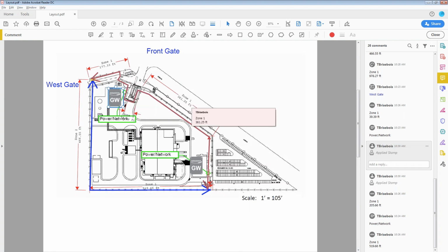One thing I do notice is that I have 2,000 feet of perimeter. So what I can do, depending on the customer situation: this area, the dark red, is pretty well illuminated from a parking lot and a road perspective, so I'm probably going to get fewer intrusion attempts on that end. I may want to go with a lower cost option, which might be Flex Zone.